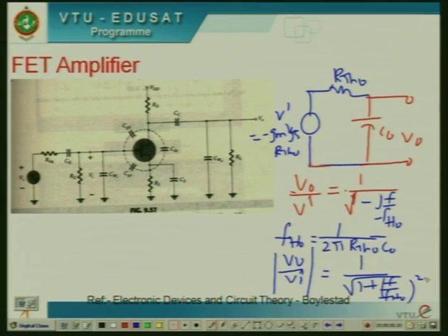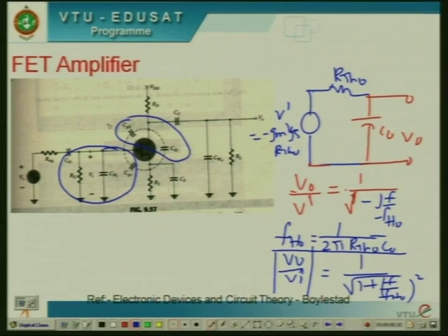Therefore, we determine both the frequency response at the high frequency due to the input frequency components, that is CGS and CGD, and also we determine an upper cutoff frequency due to the output circuitry, that is due to the CGD and CDS, given by these two expressions.